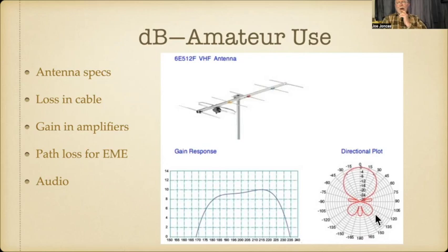But we're comparing the whole antenna to itself. In this diagram here, we're talking about a dipole. See this beam right here? That's the driven element, and that is a dipole. So you put a reflector back here, which sends a signal that direction. And then these are directors, and they're placed so that they will cause the signal to go that way.